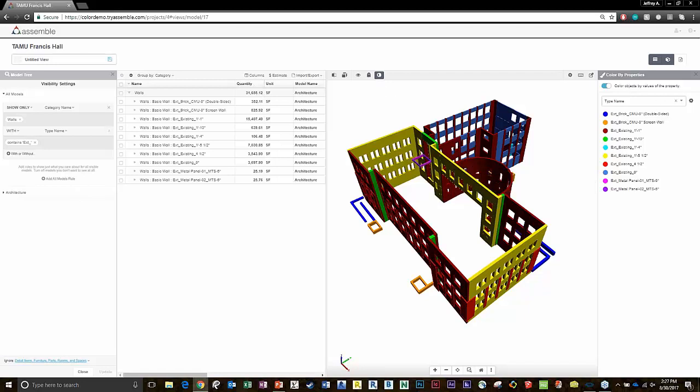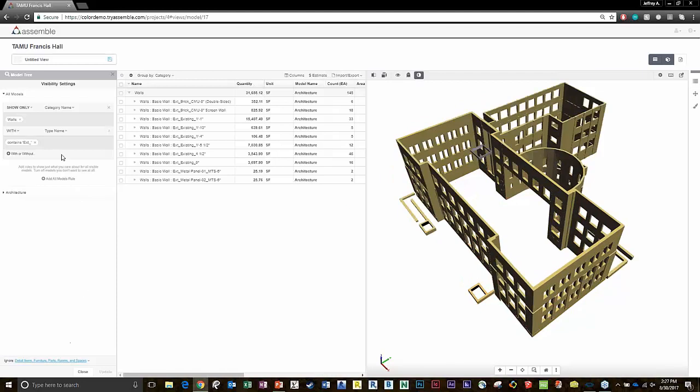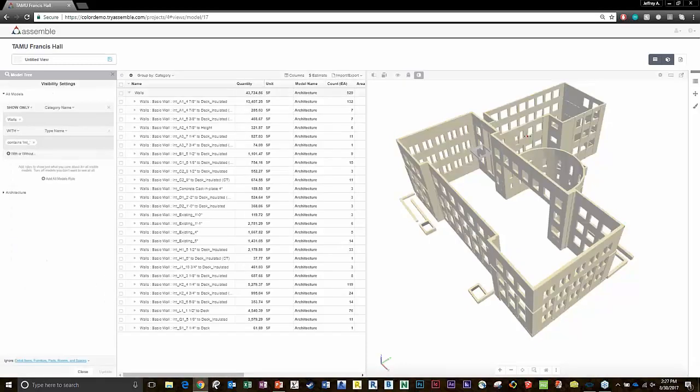So the same thing applies to interior walls. So let's close this and let's quickly take off some interior walls. I know again that this model, they use INT. So if I type INT underscore, again, if they had correct functions, we could just use function equals interior. But right there, I'm going to look for everything that contains INT and click update.